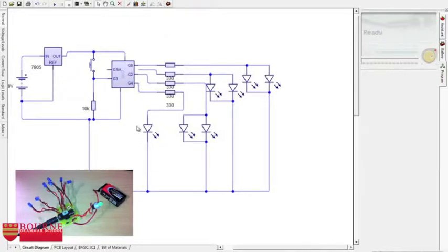For some reason, sometimes with this particular circuit, when you load Circuit Wizard up, it glitches slightly. Your Genie chip, as you might recall, we set it up to have one input so that we could have 4 outputs. For some reason, when Circuit Wizard loads up, it gives you 2 inputs and 3 outputs. So you can actually see there's a wire just hanging here. Let's start by fixing that.